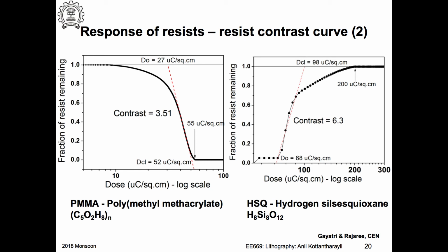Okay, and it is relative, so you are taking the maximum of the energy and dividing the whole thing by that number, so you get the maximum value to be 1. Got this point? Is this clear? Okay. So what we need to do now is we look at two parameters from the resist contrast curve, that's Q0 and QF. Okay. Assume it to be a positive resist.